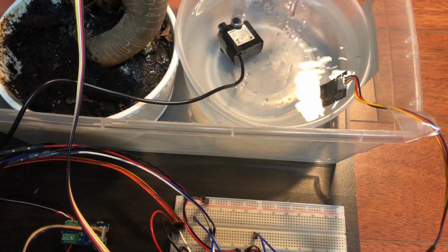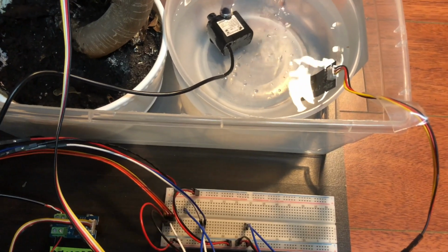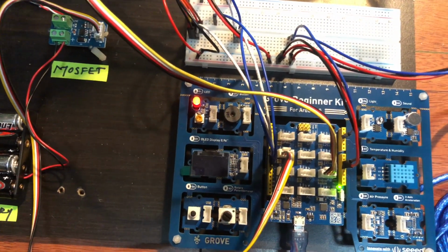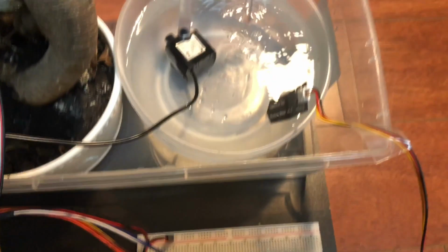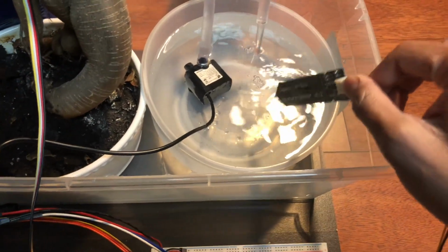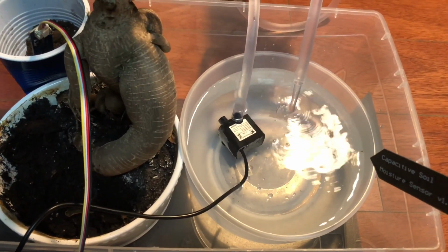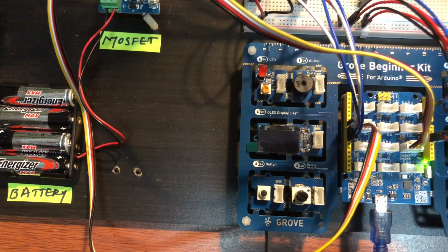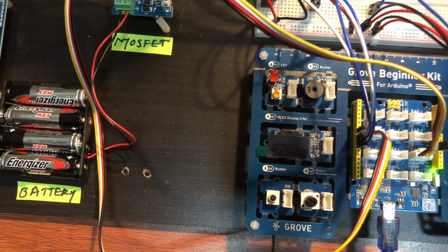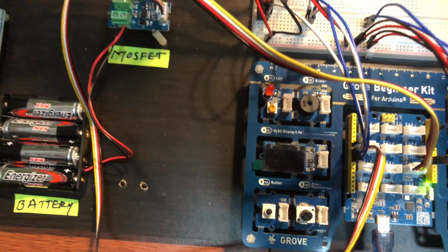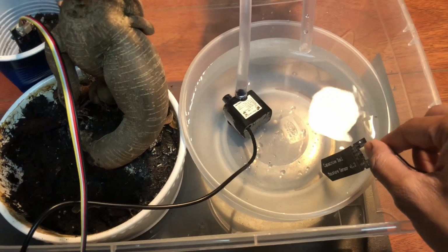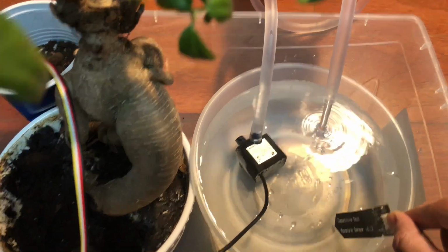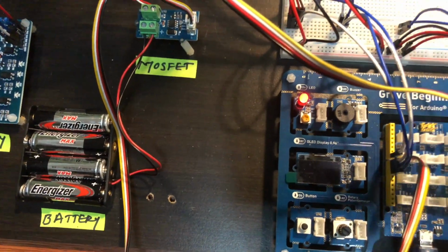Now I'm going to demonstrate how this water level sensor is going to work in this system. Once this water level sensor senses that there is no water inside the water tank, then it will turn on this LED as the warning light, it will also start the buzzer, and it will turn off this water pump. So if I remove this water sensor, then it will turn off the water pump, and now it's buzzing, which means it's giving us a warning sign. And once this sensor starts sensing water again, it will turn on the water pump. And now we can see that the water pump is on.